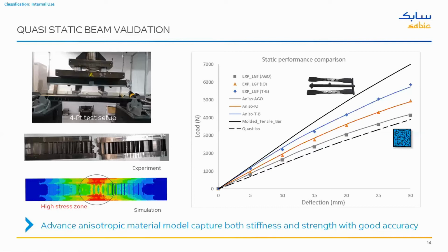And that's also something you can play with in Moldflow: find the critical area within your part where you want to align your fiber orientation, and you can design your filling sequence and the gating location such that you get a more favorable fiber orientation there. So that way the anisotropic approach of part design is much more powerful in getting better lightweight designs on the part.